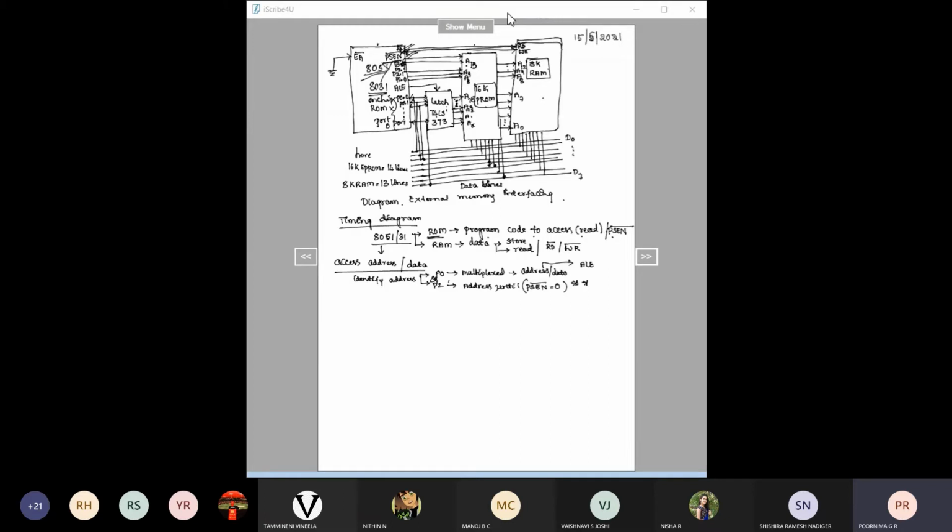So first, how this 8051 will identify the address. For that, as I told you, it depends on port 0 and port 2. So how do this port 0 or port 1, port 2 represent? Through a bus. So bus is nothing but a group of wires. How many wires are we going to connect as in port 0?